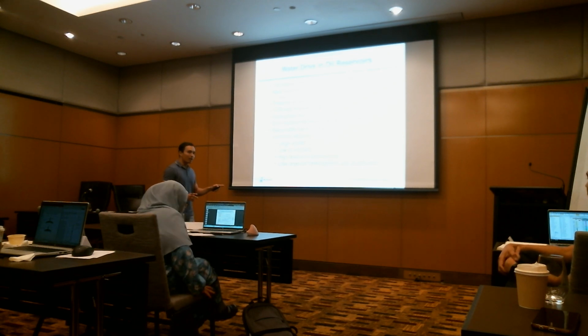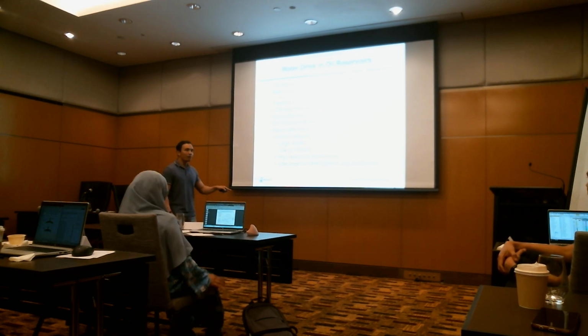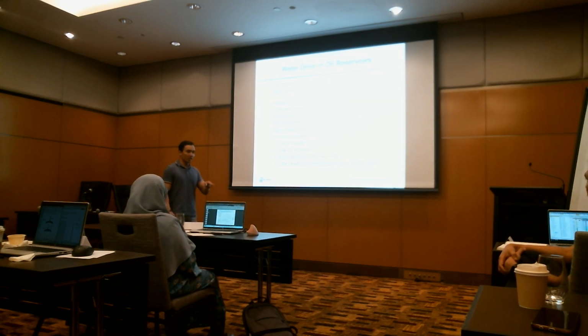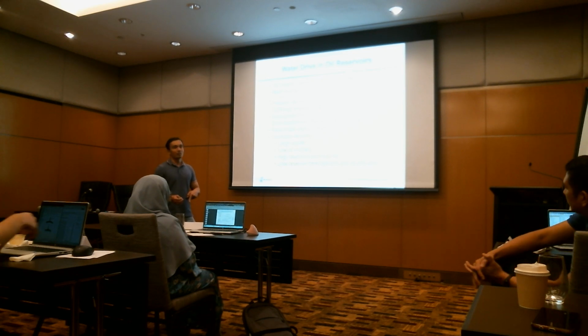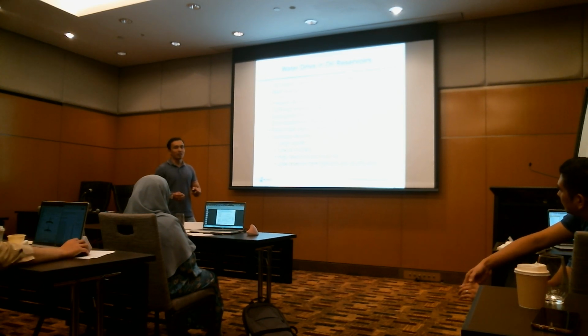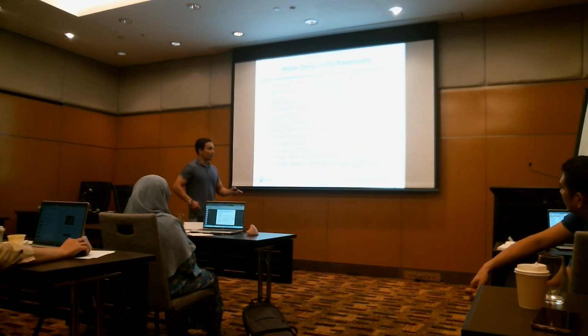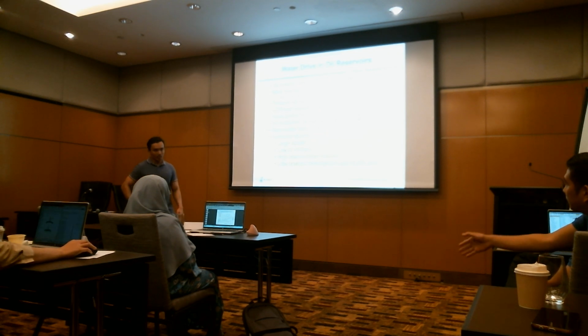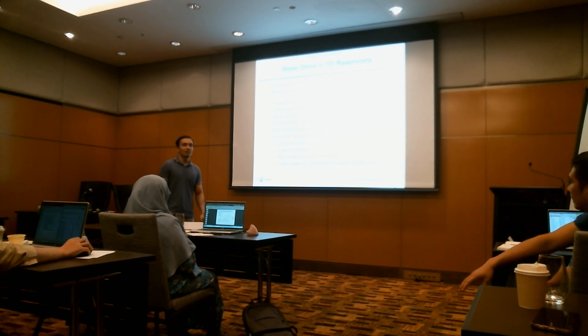From that, we can determine the average saturation at the breakthrough time, so you can know how much saturation. But that doesn't mean that if you have that saturation in the system now, breakthrough will happen. It depends, so there's an analysis that you can go through to conclude that water breakthrough has started.